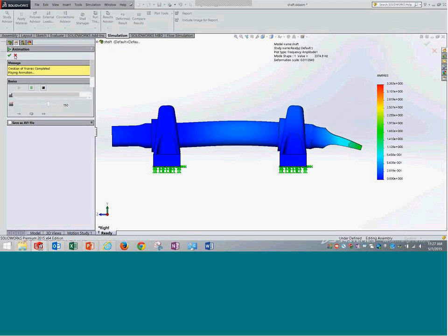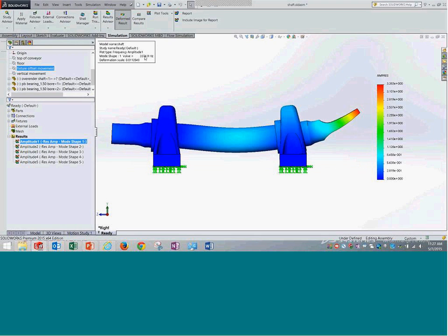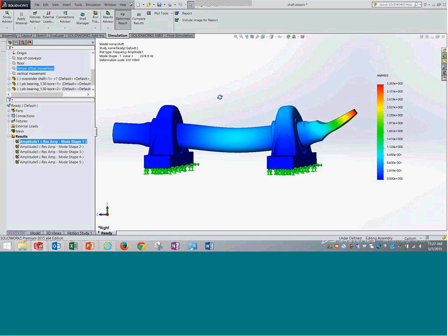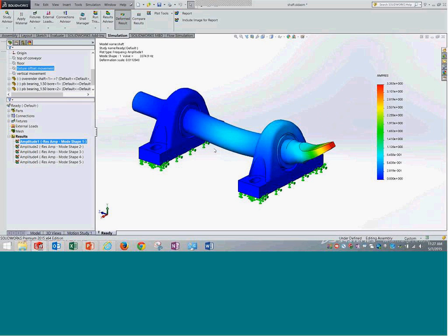So this particular shaft rotates at a frequency of around 3000 to 3500 hertz. There is a possibility of it oscillating or creating resonance in the direction shown on the screen. So if I need to design this setup, I need to avoid this particular natural frequency, or I do further dynamic analysis to understand this in more detail.